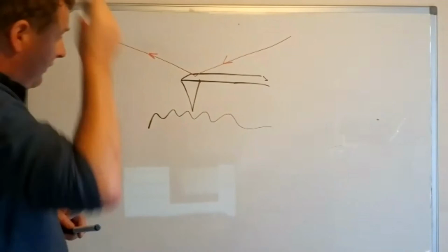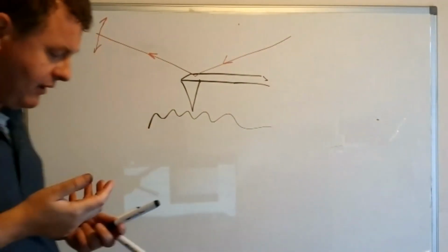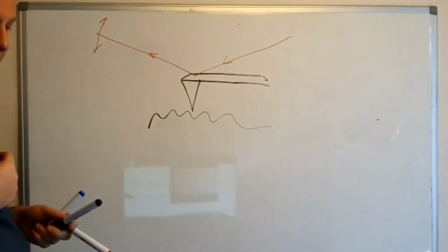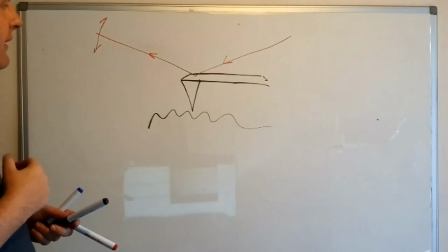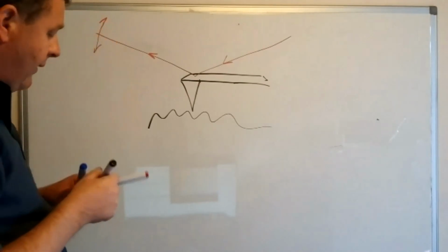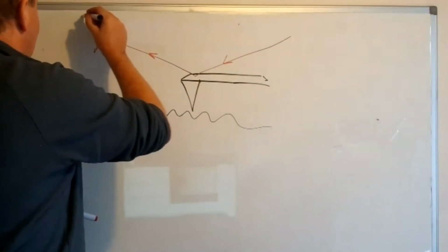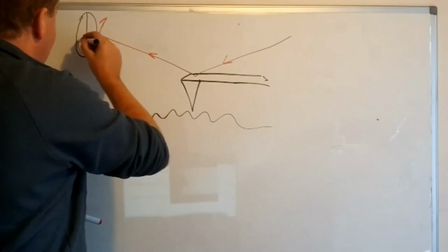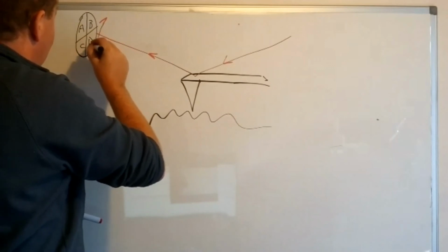So it's coming in like that. And then we have to try and somehow measure the position of that laser. So what we can do is use a photodiode. A photodiode will give us a current when light is falling on it, and not when it's not. But in order to measure that, it's kind of got a large background signal, and we want to measure exactly where it's going. So rather than just using one photodiode, we arrange to have 4 of them. So we have a sensor that looks like that, and it's divided up into 4 photodiodes, A, B, C, D.